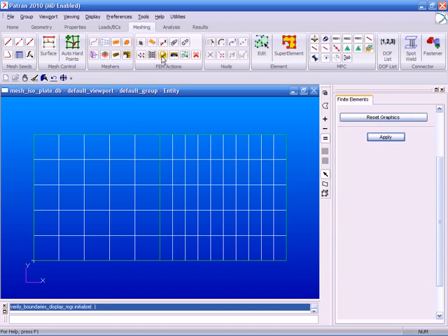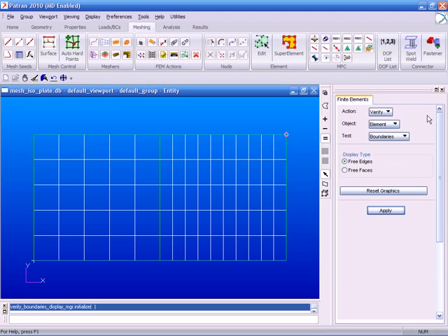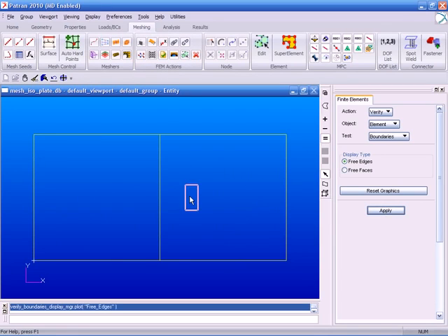This brings us to the concept of generating a congruent mesh, which is really important. So if I want to verify the boundaries of my meshed surfaces, from FEM Actions, I'll choose Verify and click Apply. I can see that this yellow line down the middle indicates that I have a free edge between my two plates. So because I meshed them separately, there are 2 separate plates that happen to just be next to each other. Now if I want them to be continuous and act as one plate with the nodes connected through the middle, what I'll need to do is equivalence the nodes.